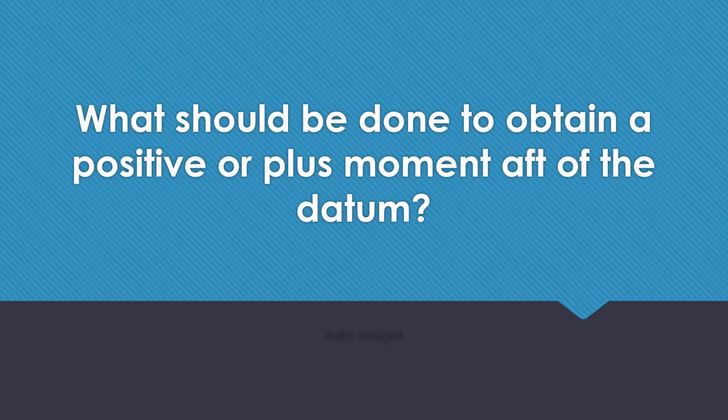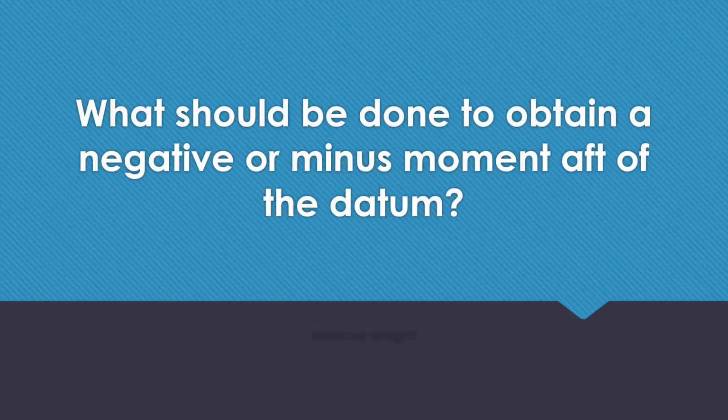What should be done to obtain a positive or plus moment aft of the datum? You add weight. What should be done to obtain a negative or minus moment aft of the datum? You would remove weight.